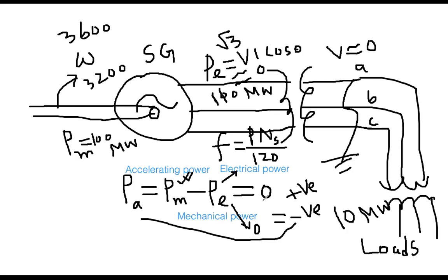So this means when the result is positive, when it is acceleration, shaft will be accelerated, consequently speed increase and then frequency increased. On the other hand, when you are injecting loads, because Pe getting increased, it is overloaded, it is facing much more burden, consequently system will be decelerated. Because speed decelerated, your frequency will be decreased.